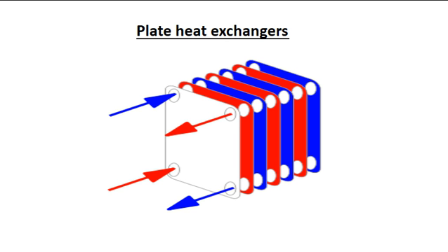Plate heat exchangers also differ in the types of plates that are used and in the configurations of those plates. Some plates may be stamped with chevron, dimpled or other patterns, whereas others may have machined fins or grooves. Plate heat exchangers also come with plate fins.